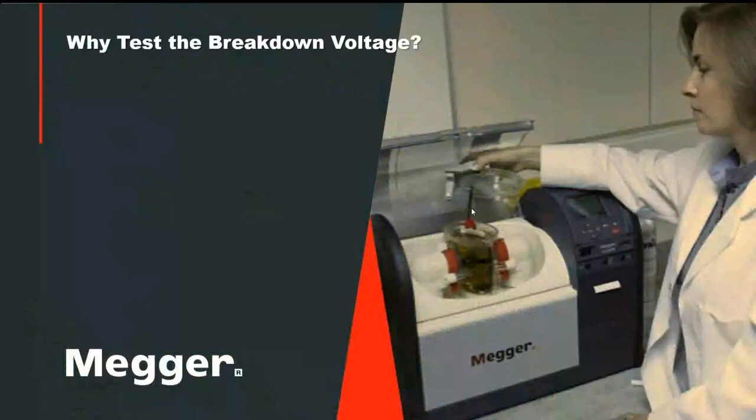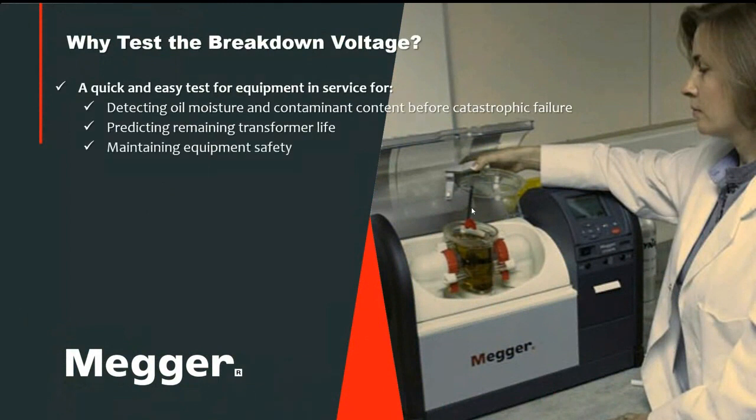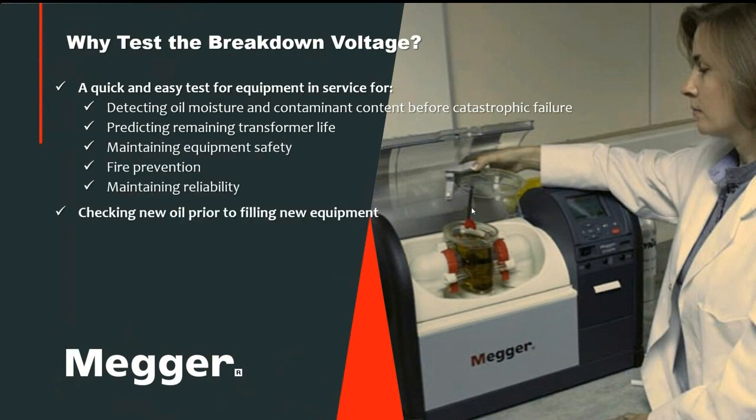So why breakdown voltage? Because it is the easiest and quickest way to test the oil for detecting moisture and contaminants, predicting remaining transformer life, and of course maintaining equipment safety, fire prevention, and maintaining reliability.